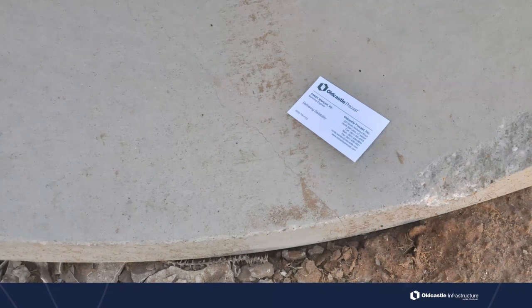It caused a lot more work to remove and replace that section of pipe, but the owner asked us to do that, and as we pulled it out, we evaluated and noticed it really should not have been removed. This was an acceptable crack. It was within the specifications and the acceptable limits. Now you might say, well, what about the chipped bell there, that issue at the joint? That was actually done as we were removing it, so we caused more damage to the pipe removing and discarding it than we did when we put it in the ground. So that came after as we were removing it.